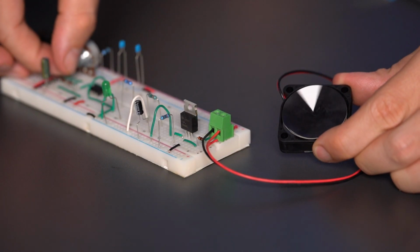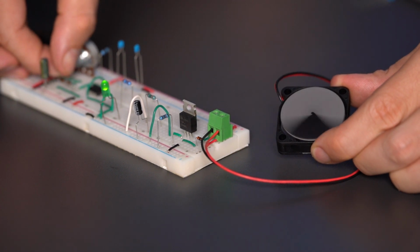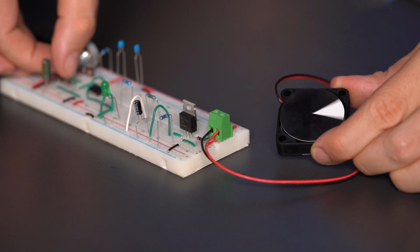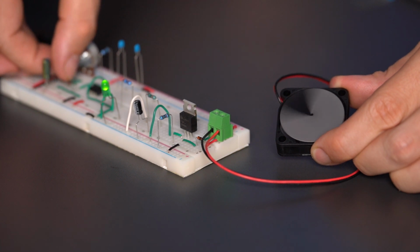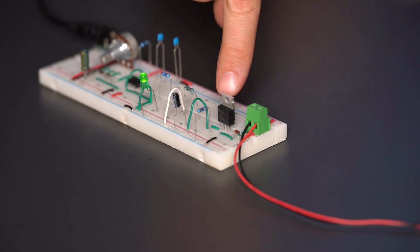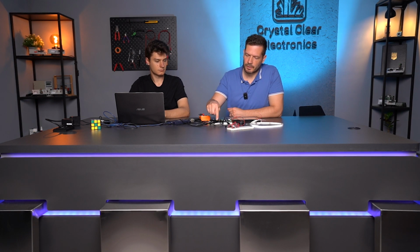I start to increase the PWM duty cycle. You can see that when I turn it down, the motor basically stops. And if I increase the duty cycle, I can increase the motor speed nicely. We can hear it humming, and this is where the FET takes place. The idea is that the relatively high current from the motor will not flow through the 555 IC, but through the FET itself. I assume that we have one more interesting fact before we finish this video.